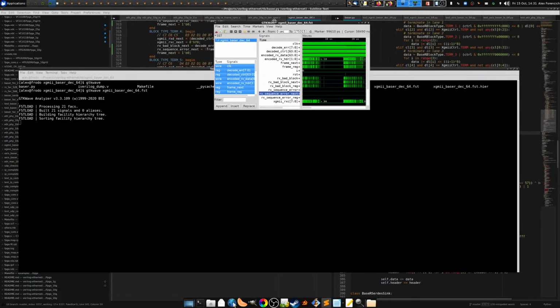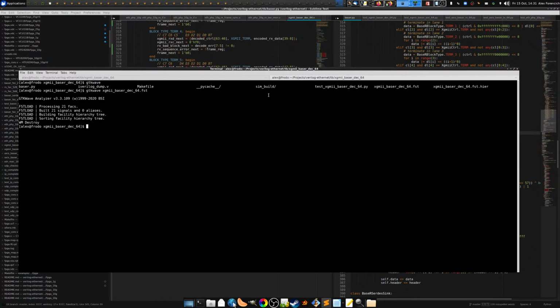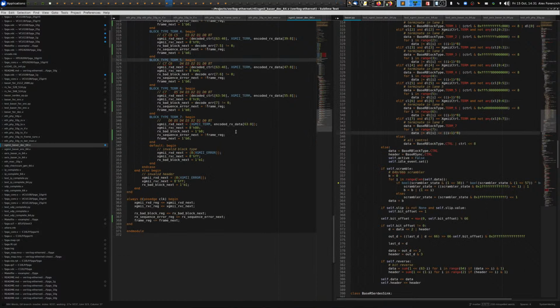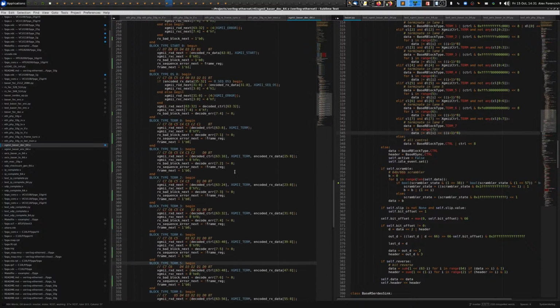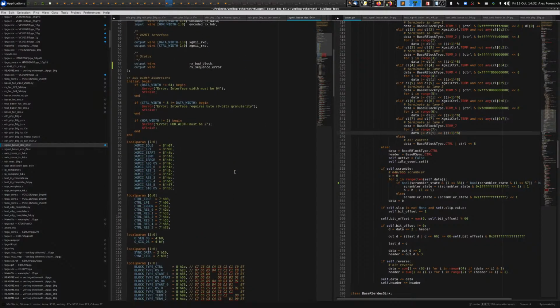Now what we need to do is put together the higher level component, the actual Watchdog. So there's two components to this, right? The first one is looking at all of these various aspects of whatever's coming out of the SerDes, the 64/66 blocks, checking to make sure all of the encodings are correct, and that we're seeing the sync headers that we want to see. The next piece is collecting all of this information and generating the reset signal that's going to cause the PHY to reset itself.